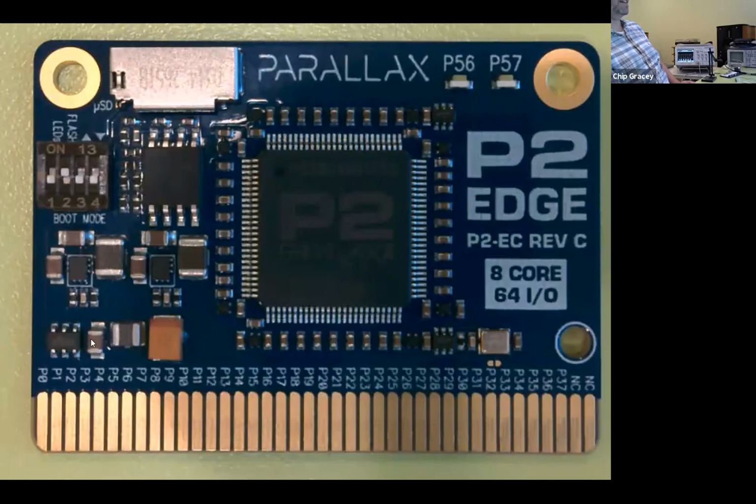Then we have a cap to ground. We have, I believe this is a ferrite bead. And then we have a secondary bulk cap. And then off this bulk cap, these two switchers feed. So that generates everything. And down here, we have our new clock. This is this temperature controlled crystal oscillator that's good for 500 parts per billion. And it's a clipped sine 1.8 volt device.